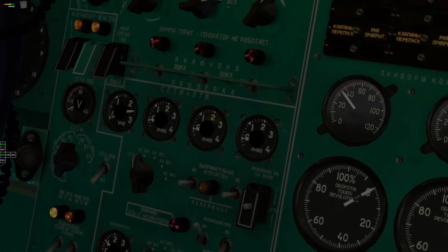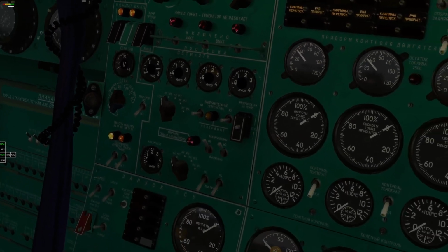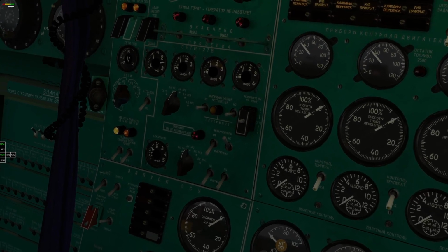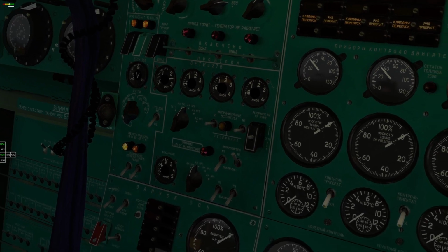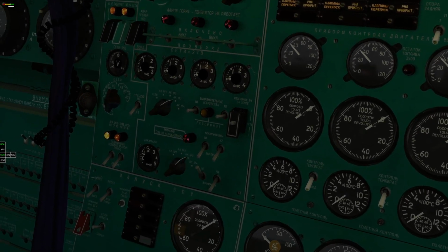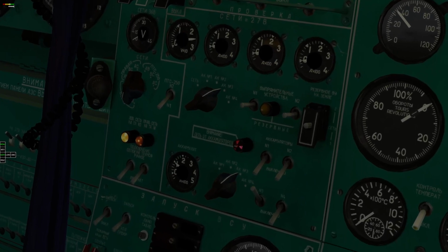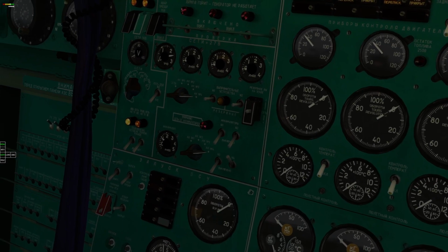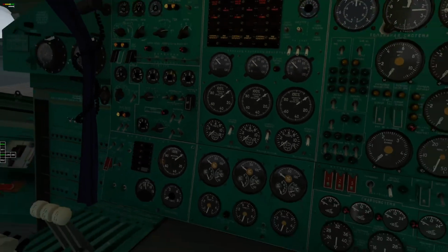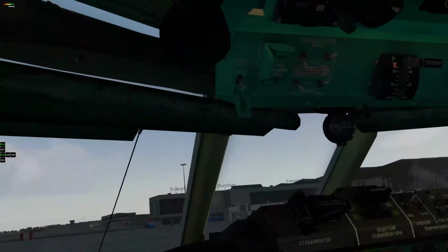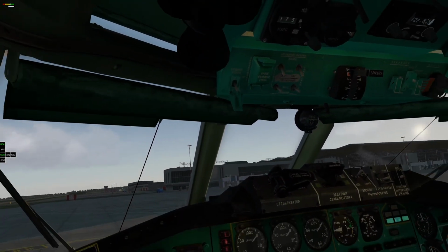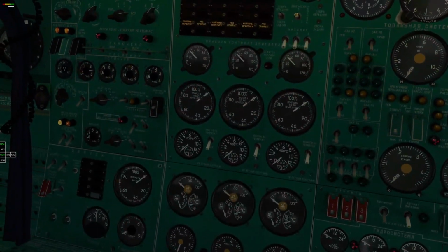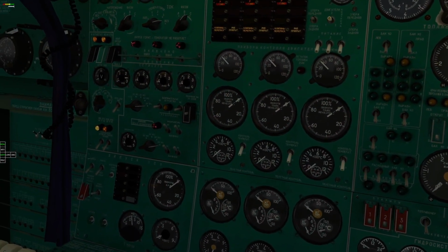We have no lower than 24 volts here. Number 2. Switch this to number 2 also. 100 amperes. No lower than 24 volts. Number 3. Number 4. Looks about right. Now I can turn off our landing and taxi lights, and turn all our batteries on again.